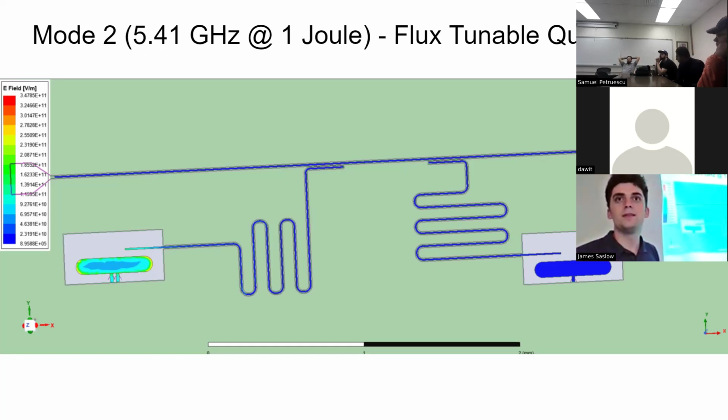Is that what this simulation is doing? You're putting a voltage at one of the pads, right? And sweeping a bunch of frequencies, and then this is showing us that when you hit 5.41 gigahertz at the pad, that energy is being stored in that part. Exactly. Yeah, that's exactly right.